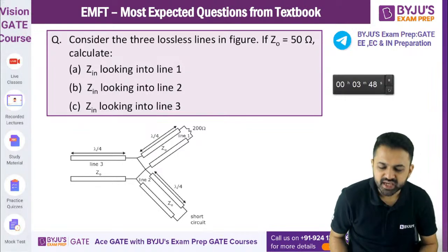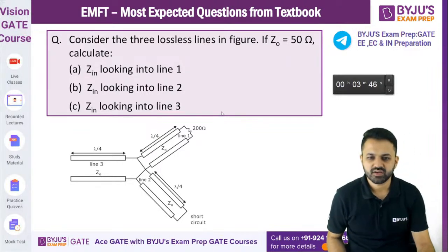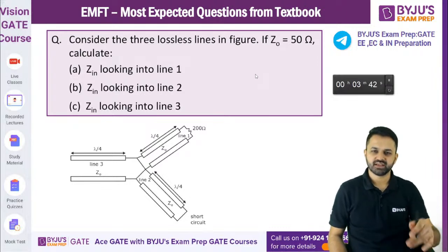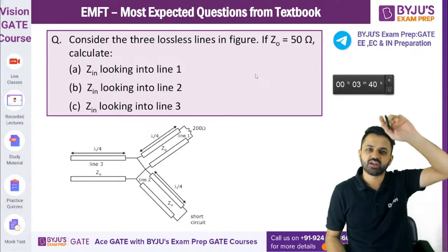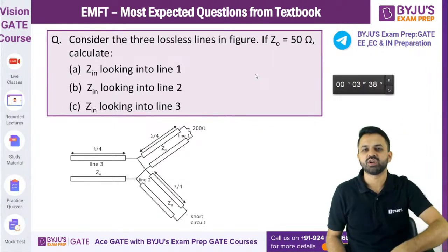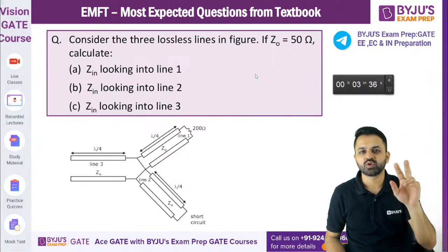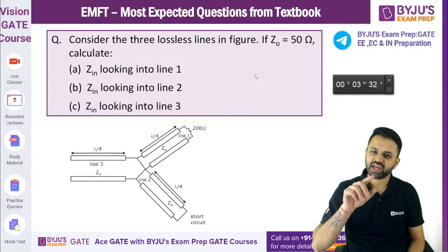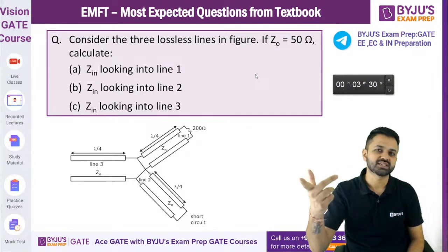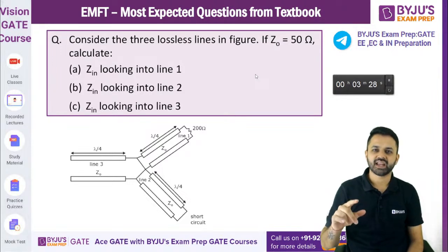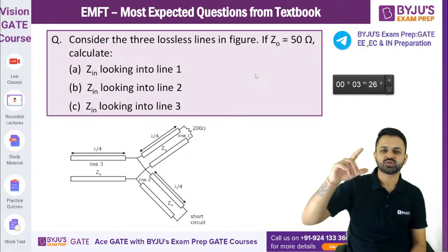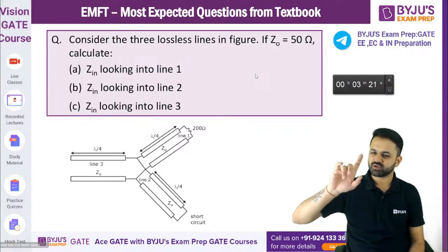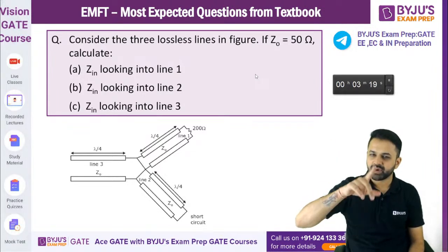Ayush, because it is a peak value, no? We write in terms of VRMS into IRMS. Then in terms of peak value, VRMS is equal to V naught divided by root 2, and then whole square. So I square into R, so that I is nothing but IRMS square. IRMS is converted into the peak value. So that is why I naught divided by root 2 whole square will come. So that is why I naught square divided by 2 came.